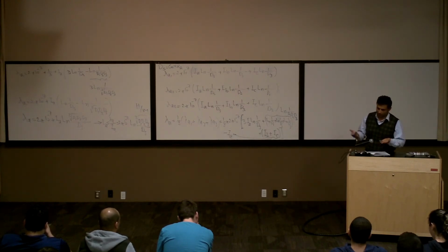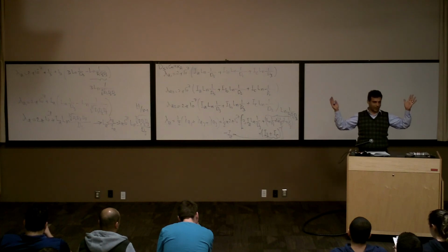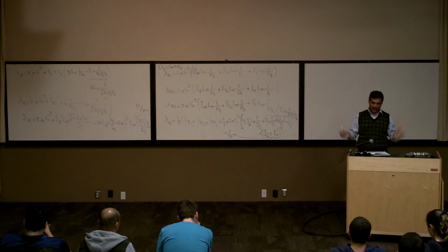To fix the problem, to reduce the ohmic loss, to prevent the wire from burning, we say, hey, use a bigger wire. If you use the bigger wire, the resistance is less, the power loss is going to be less, and there's going to be less heat generated inside the conductor, and it's going to protect the wire, right? Now, when we have a big transmission line, it's going to transfer a gigawatt or so, now we are going to deal with a huge current.